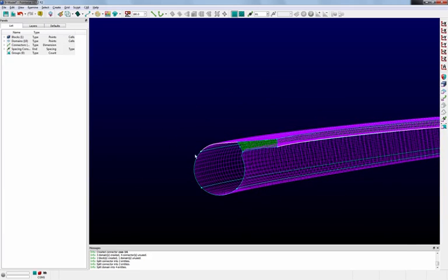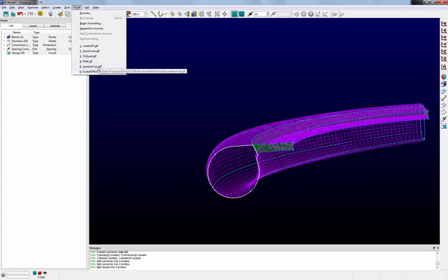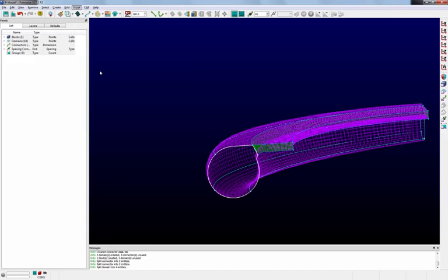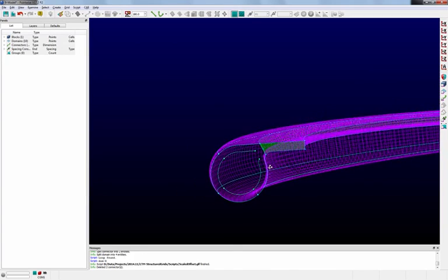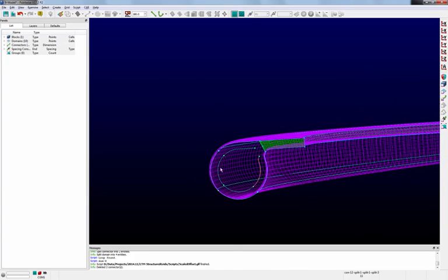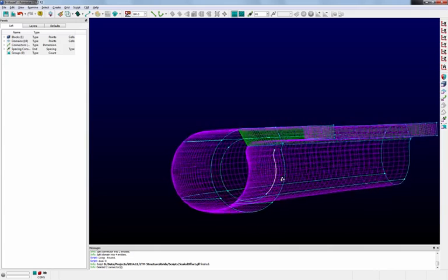So the next thing that we want to do is create that boundary layer block. What we can do is, again, use a script to help create that. You can try extruding this, but because it's kind of an odd shape, it's a little easier for me to actually just generate by hand. So we're going to highlight this and run this other script that I've written called Scaled Offset. This has a hard-coded parameter that you can change that's currently set to 0.75, and it just scales the loop of connectors that you've passed to it by 0.75, with respect to the centroid. So it's just going to scale that and create these new connectors right there in the middle.